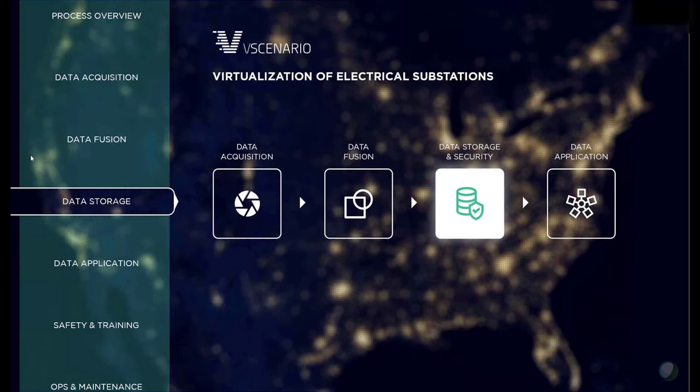The good thing about having all of this mapped originally to one coordinate system is that any other spatial models are just plug and play. Let's say that on the southeast corner of a substation, we've just made some changes. We want to make sure we get that into our model. Instead of having to start over and do ground penetrating radar all over again, fly the drone again, and do the laser scanning everywhere, we can just deploy the laser scanner right there, fly the drone right there, and that all gets mapped to the exact same coordinate space. So great question, that's a really good point.